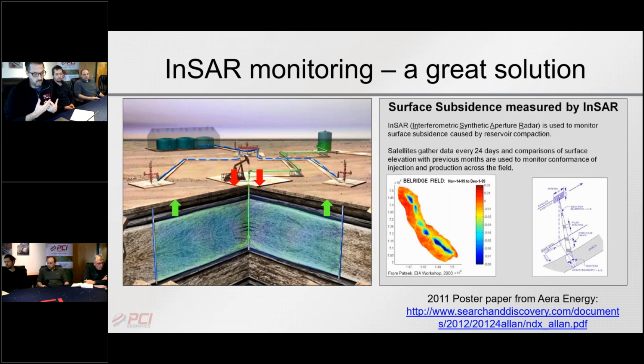So of course, this is very expensive equipment. These particular wells here are on the order of hundreds of thousands of dollars, if not millions. And what oil companies are really concerned about is movement of the subsurface up or down, so subsidence or deformation, because if you get too much subsurface material pushing down on pipes, basically it can cause the pipes to shear, and then that would render the well kind of useless. So very expensive to replace. And obviously they're trying to avoid that.